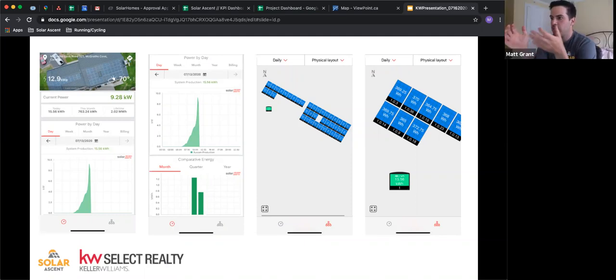So I'll explain the whole bidirectional metering arrangement. As part of the Nova Scotia Power process, you'll get a net metering agreement. Once the system's completed, a Nova Scotia Power meter person will show up and install a bidirectional meter, which measures the flow of power coming in and going out. Homeowners are given credit at the retail rate. With solar, you're looking at it over an annual period, because obviously your production is going to vary.